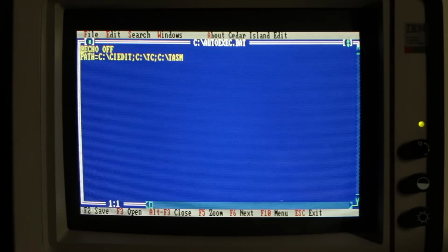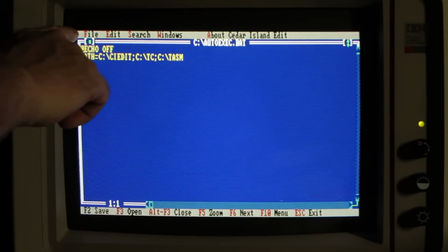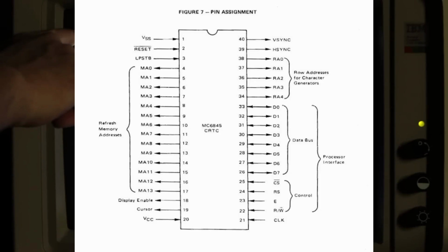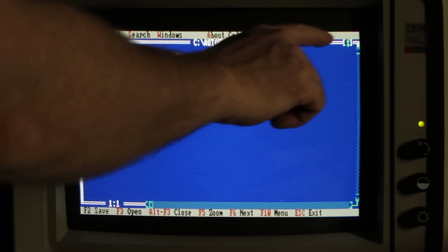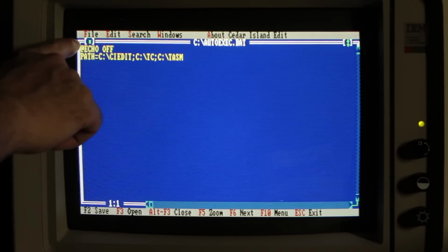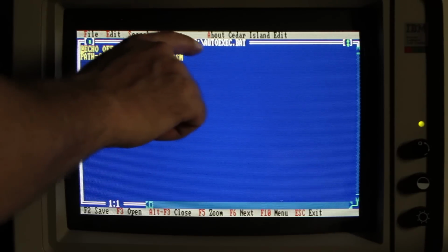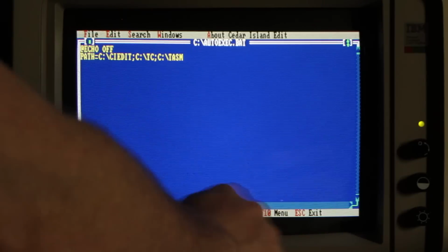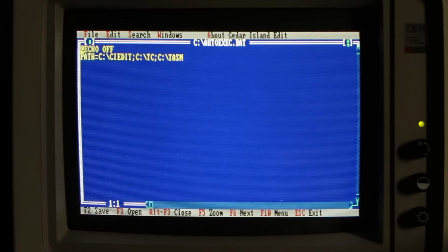For the text modes, the CRT controller chip is outputting a character address which gets incremented for each character position on the screen. It gets to the end of the first character row, and when it starts the next character row, it just continues to increment that character address all the way to the bottom of the screen.